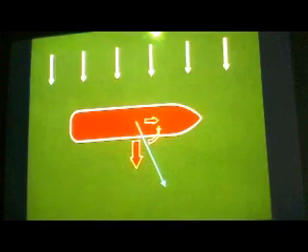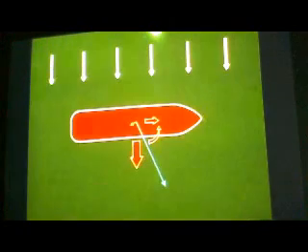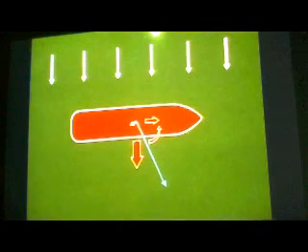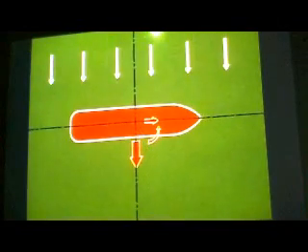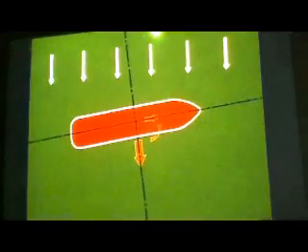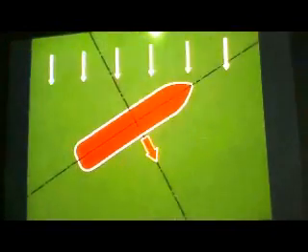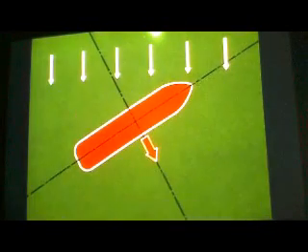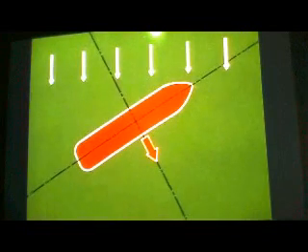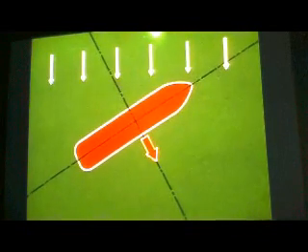The blue arrow shows the vessel's track. The Earth's rotation generates the well-known Coriolis force, which in the northern hemisphere acts to the right. Coriolis always acts at 90 degrees to a vessel's track. Since track speed is low when drifting, the Coriolis effect can alter the track according to latitude. Subject to these forces, the vessel now turns to a new heading. This balanced steady state is represented by the equilibrium ship's heading, drift speed, and direction. And under these conditions, the vessel is sailing.